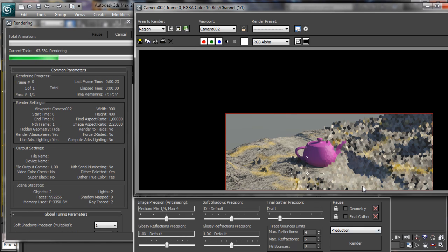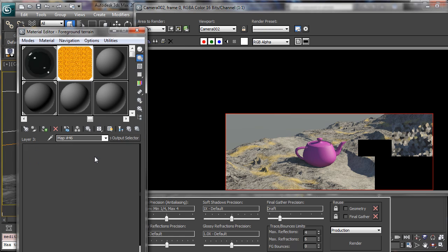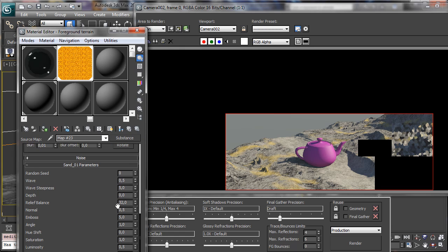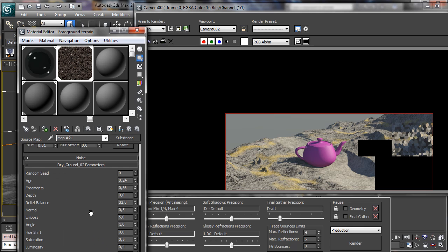Okay, stop the rendering. Then we can fix the color for this one. And let's say that we have the saturation set to 0.5 and the luminosity to 0.4, and let's have a little bit more saturation there. Let's try with 0.55 and render.